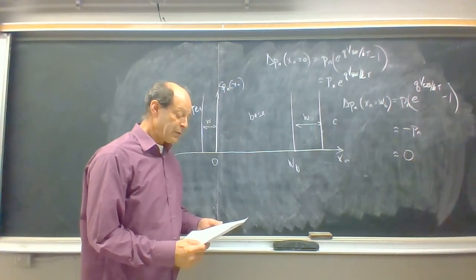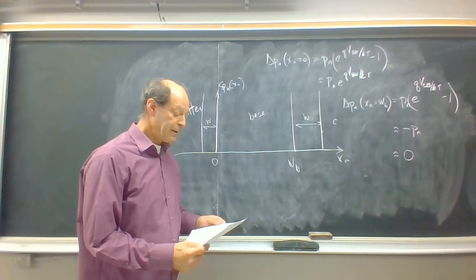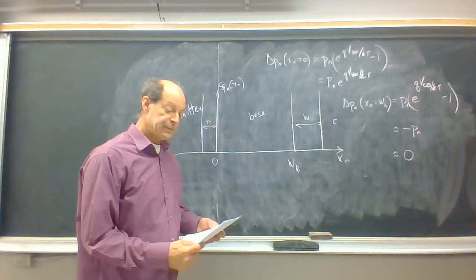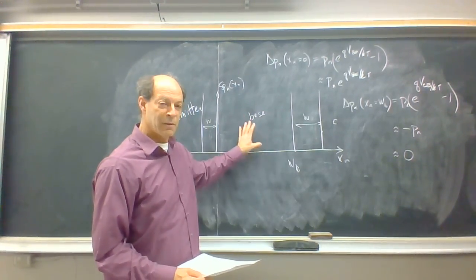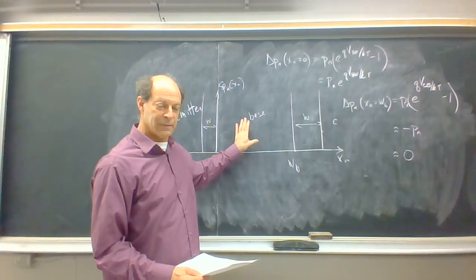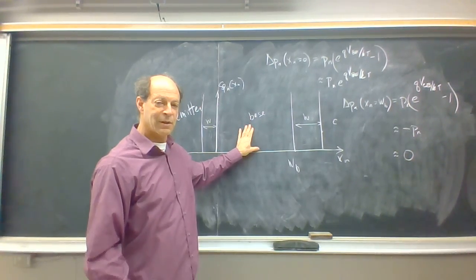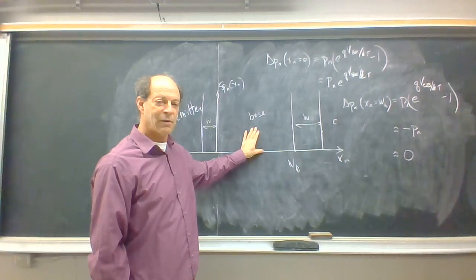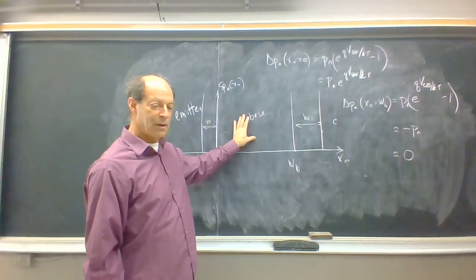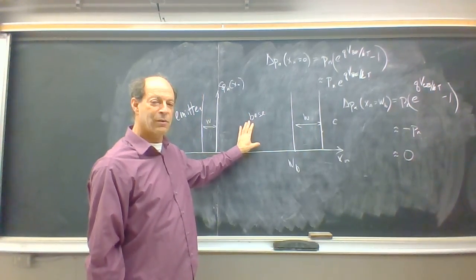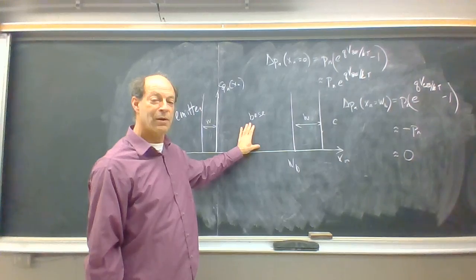So we can now put together the diffusion equation because we're going to make the assumption that the base itself does not have electric fields in it. We wouldn't expect an electric field in the base because the electric fields would all be in the depletion regions. The base would have current flow due to diffusion, just like in a regular p-n junction.